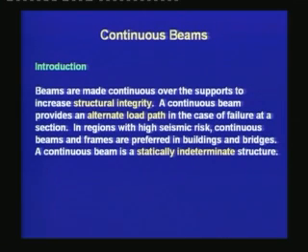Continuous beams are made to increase the structural integrity so as to have more redundancy in the structure. So, in case of a failure at a particular section, there will be an alternative load path for the load to go down to the support of the structure.